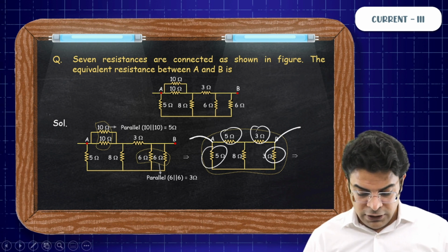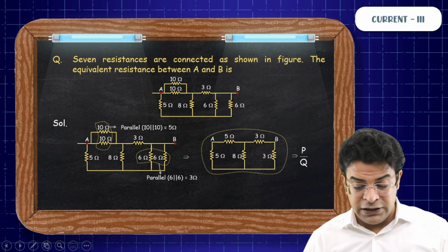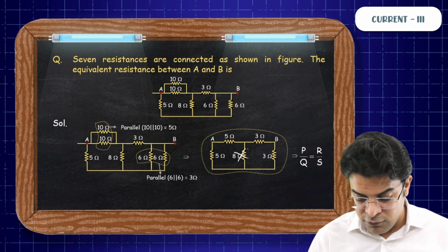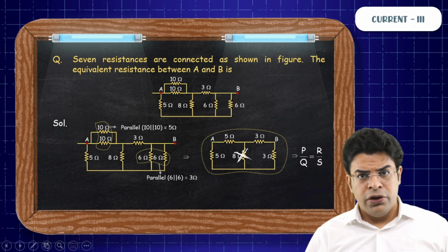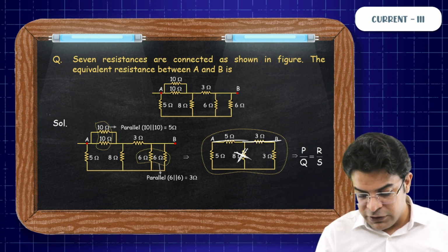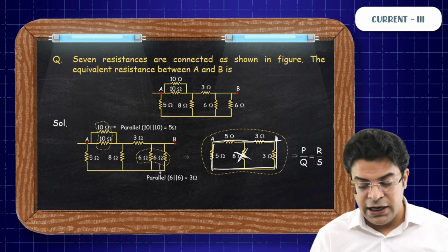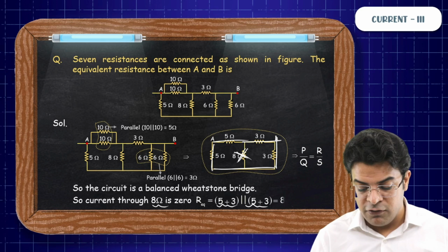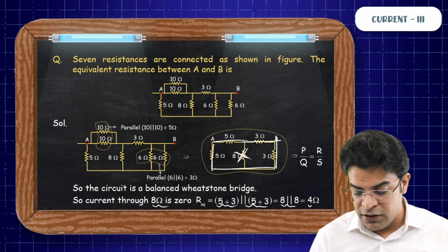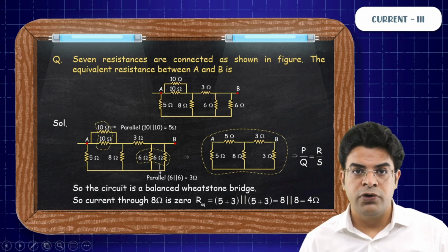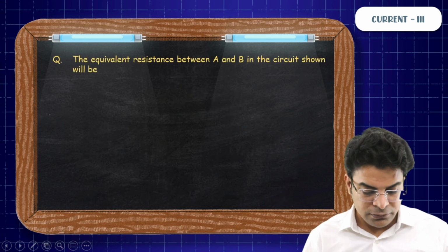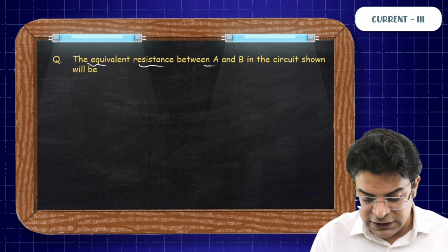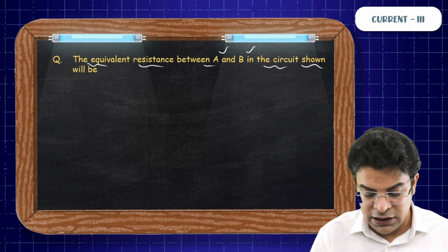Once you can see this balanced Wheatstone bridge, you can say that no current flows through this 8 ohm. So in the upper line, resistance is 5 plus 3, 8. In the lower line, 5 plus 3, 8. So the R equivalent of this circuit is nothing but 5 plus 3 parallel 5 plus 3. That comes out to be 8 parallel 8, that is 4 ohm. Okay, next example. The equivalent resistance between point A and B in the circuit shown will be...